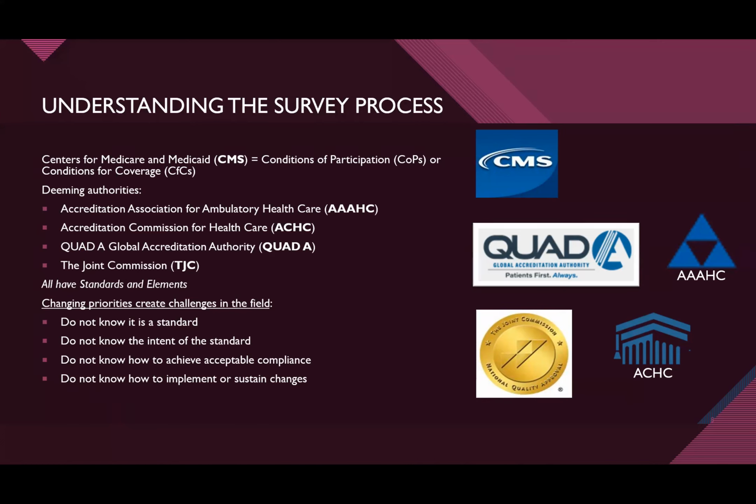And then when we open the generator and take a look inside, you can see leaves and debris inside the generator. Okay, so when people are looking at that weekly, that needs to be cleaned weekly because if the generator runs and you need it, it's going to be hot. And you just don't want a generator fire when you have people under general anesthetics.